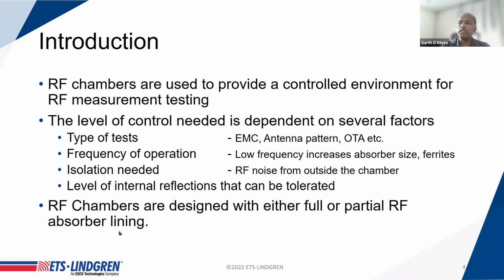In some cases, it involves antenna pattern or some type of over-the-air communication tests, where you want to make sure that the environment within which you're testing a particular device is free from outside interference or is not able to interfere with other things that are happening outside of the measurement environment. So that defines the level of shielding that's required in one aspect, but it also defines the level of reflections that can be tolerated within the test environment.